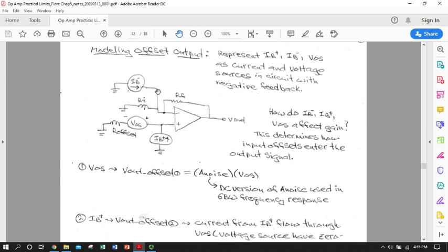Yay! We use that to do everything, right? So here's an idealized circuit model that is used to analyze the effect of these differential non-idealities, these asymmetries. This isn't necessarily exactly how you will have your circuit configured, but just about any type of op-amp can usually be equated to some variation of this by zeroing out or adding different resistors. So we've got non-inverting and inverting negative feedback configurations all taken care of here. This is a one-size-fits-all model circuit.